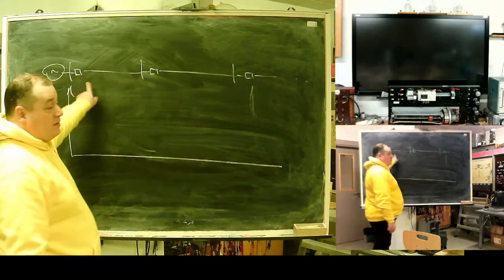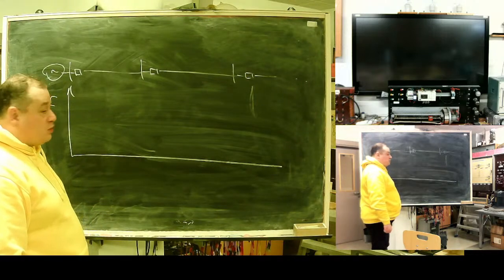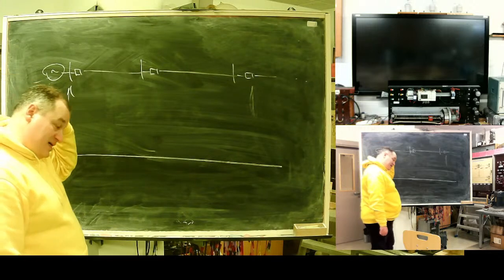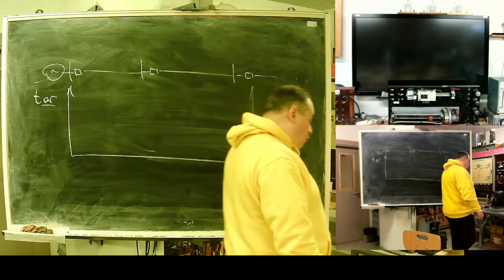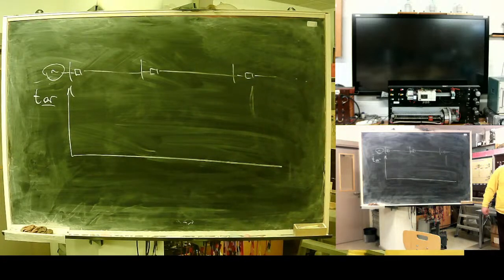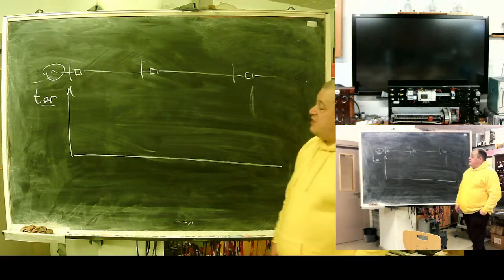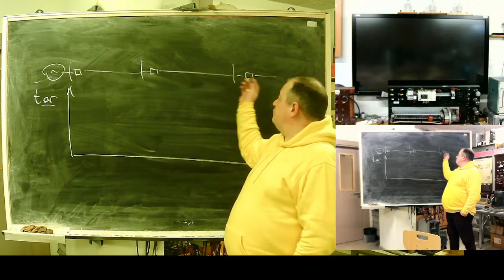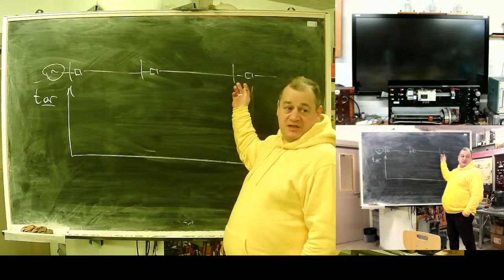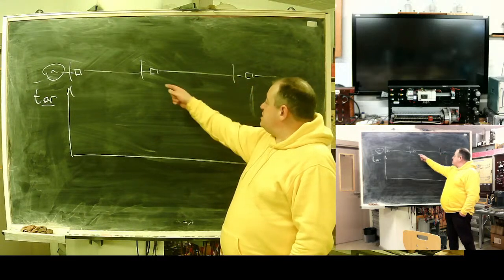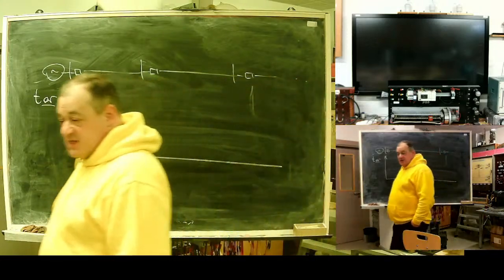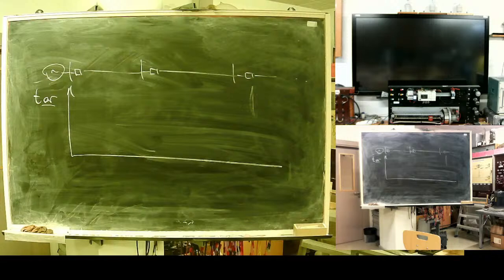At the supply. We should think in the way of, okay, resilience isn't the best word here, in the way of safety. In case, for example, the fault was here, but we had a problem with this relay and backup protection operated. This means that it's possible that all the switches are disconnected. It's bad selectivity, but sometimes it happens.